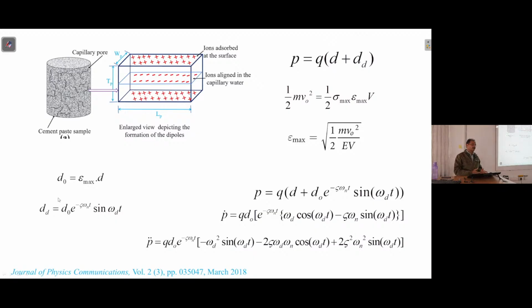So we considered the potential energy associated with the falling weight. That energy is imparted, and that produces a strain. So we just converted this input energy to the strain energy of the sample. From there we got this expression of the maximum strain that could be produced. Then we translated this to these dimensions. Epsilon max for bulk we considered, and we translated this directly to this.